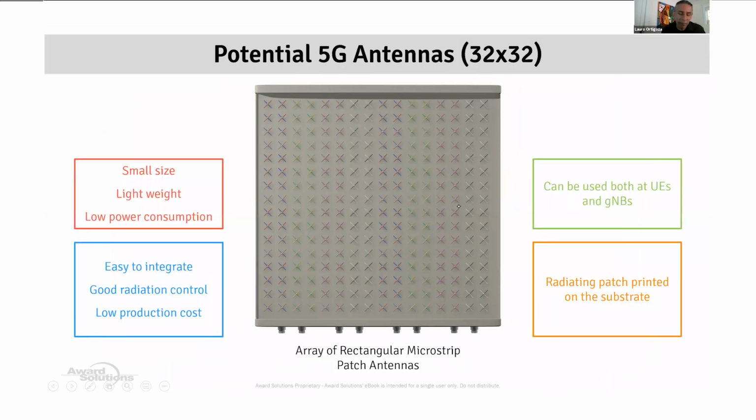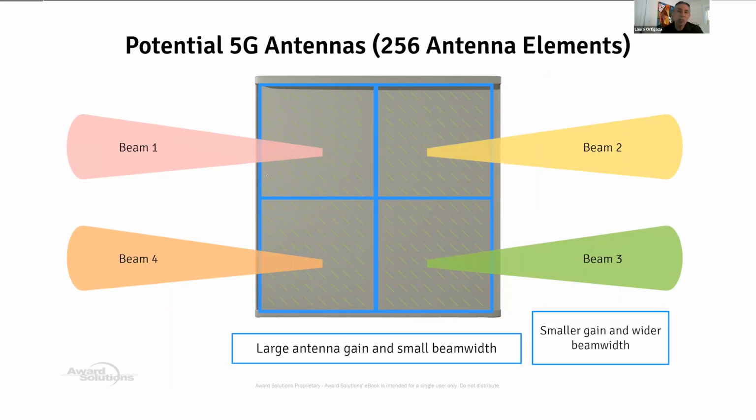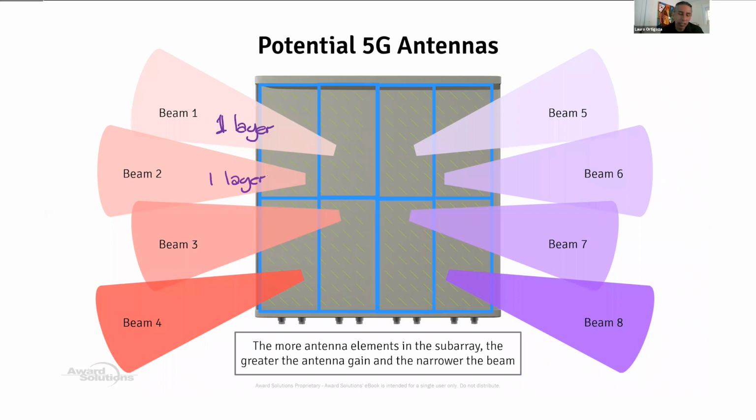Okay, so hopefully this is making sense so far. And this is just a table that shows you what happens with the size of the antenna elements and why in frequency range 1, we don't have that many subarrays. Because look at the size of one antenna element at 1 gigahertz of operation. This will be the size of my antenna element, 15 centimeters, and they have to be separated by 15 centimeters.